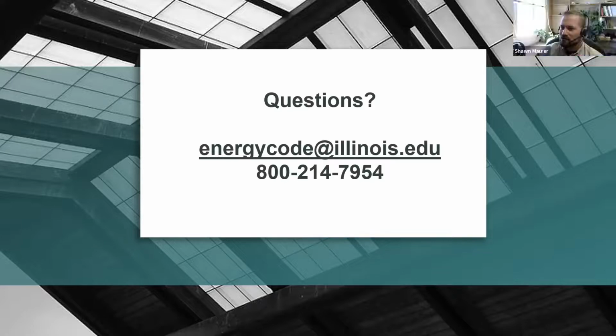Next question, air control versus vapor control. Let's be clear, drywall, well executed, is an air barrier. I believe you're talking about vapor control layer. So yes, the discussion about drying in a facility does touch on the vapor control layer, but the code does specify in its language for the air barrier that it's an or, either the interior, the exterior, or integral, not an and value there.